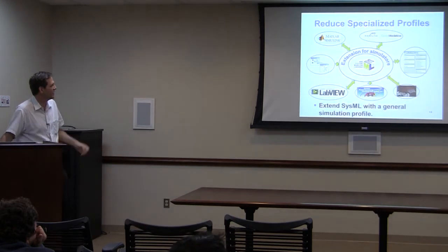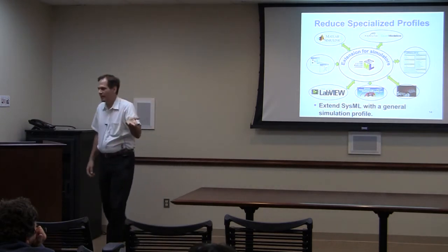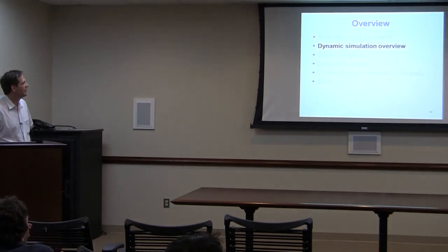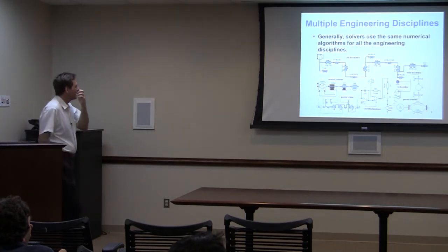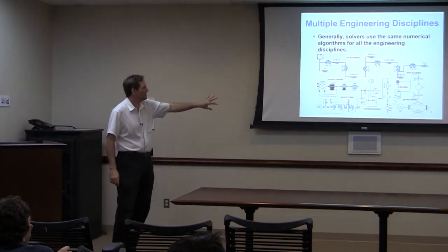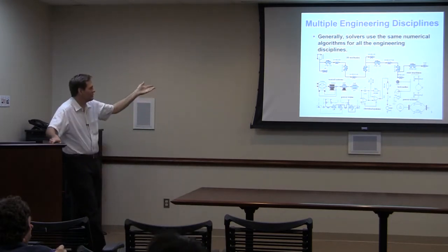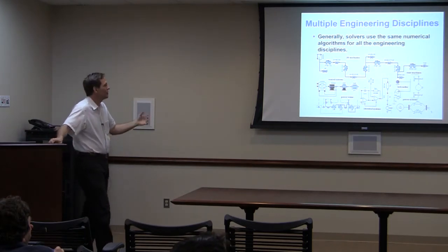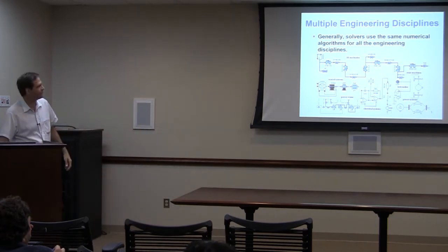So that's the general idea of what I'll be presenting today: this extension of SysML that captures what's in common between these various solver-based simulators. To understand what that is, we have to review these simulators and what they do. Since all of these different domains, whether they're hydraulics or powertrains, have specific notation that looks domain-specific to the engineer, actually the simulation tool underneath uses all the same algorithms because it's all the same equations.